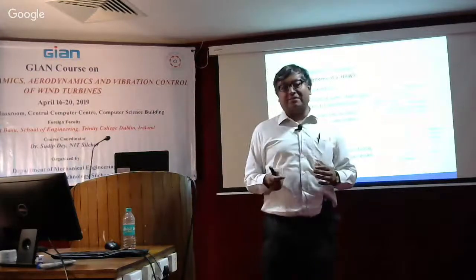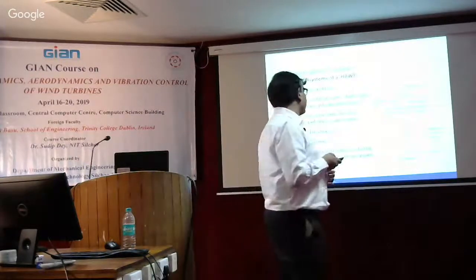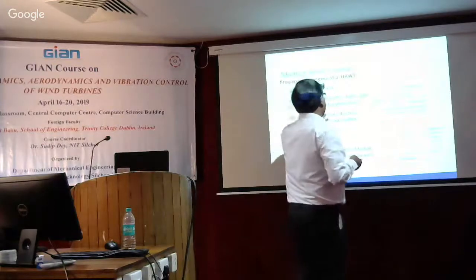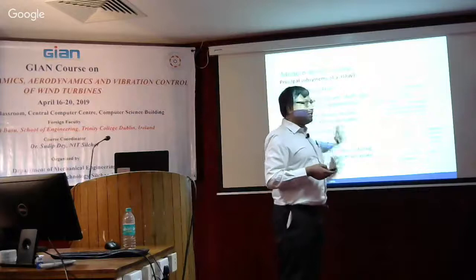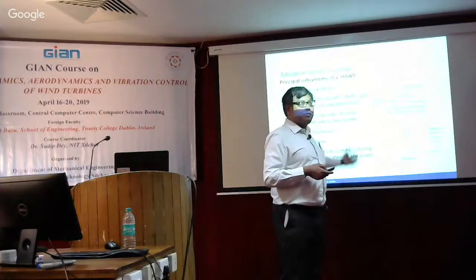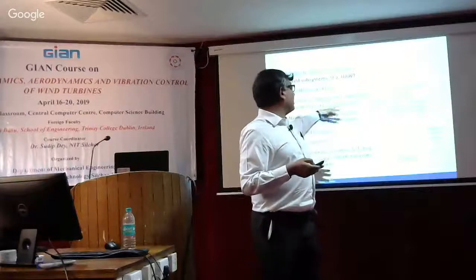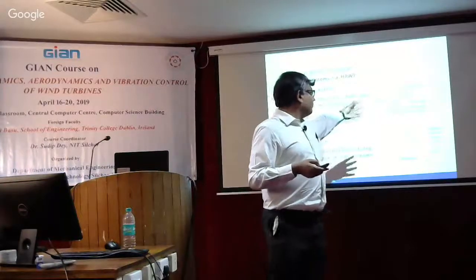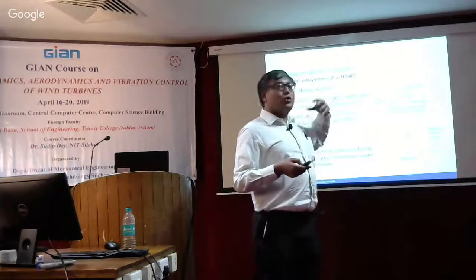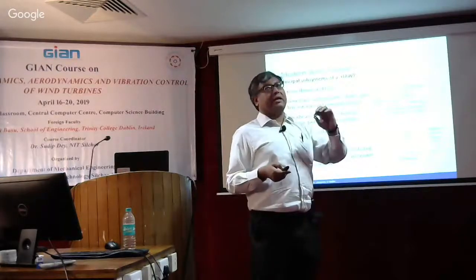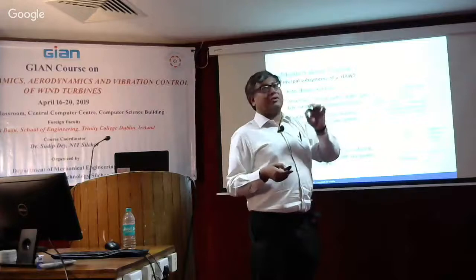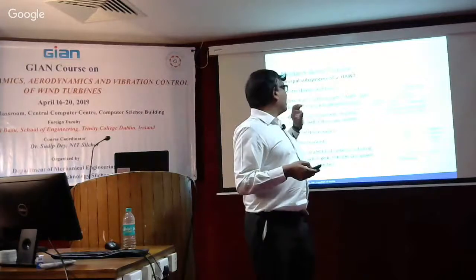And in terms of the dynamics of the systems and time scales, we are operating at very different time scales. If you're talking about the low speed side, we've seen already that the rotational speed is of the order of seconds. Most of these flexible systems, gearbox and those kind of machineries will show certain defects, which are of the order of, say, kilohertz, 2 megahertz.